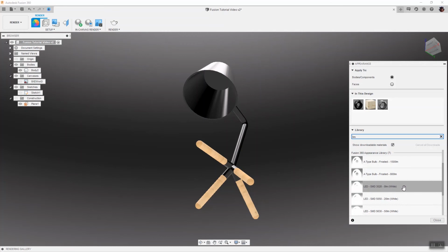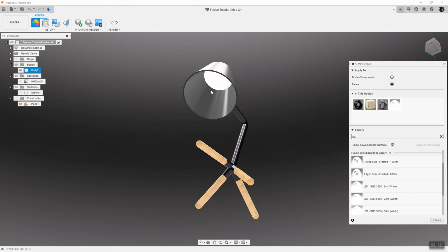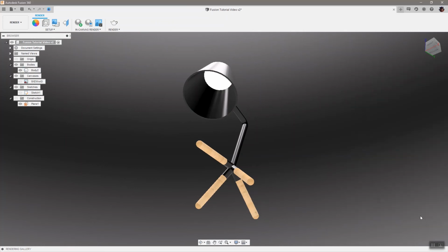It's a very small lamp. So I'm going to again say faces only, and I will pull an 8 lumen light to that surface. Now, in reality, that surface is not an LED. I have a little ring of LEDs in here, but I don't want to model those, and I'm trying to make a concept model. So let's close that again.